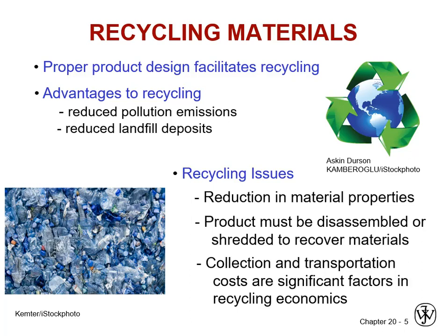Regardless of whether or not there is a reduction in material properties, products will have to be disassembled. Most products, especially composites, have multiple materials. For optimal recycling and optimal retention of original properties, you typically don't want to blend these. If you do blend them going into a recycling process, you'll tend to have to add more energy to do so. So disassembly, shredding, sorting is inherent in the recycling process.